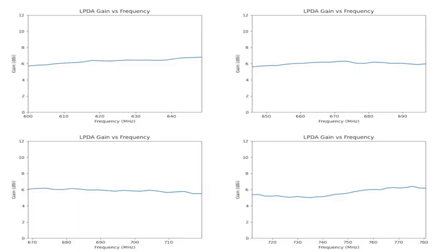14 dipoles of different lengths were used to find the gain of the LPDA antenna from 600 to 2000 MHz. These dipoles were shortened to move the valid regions of the antennas throughout the 600 to 2000 MHz range. The valid regions of each antenna were determined automatically by the computer and the corresponding valid results were saved. These valid regions were then graphed so we could compare the results with our expectations before the antenna was further shortened.